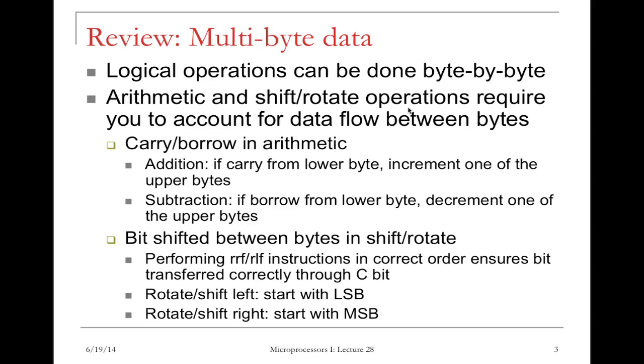Bit shift between bytes in shift and rotate. We'll make sure that the rotation instructions will go through the carry flag. For rotation shift to the left, we're going to start with the least significant byte. And for the rotation shift to the right, we're going to start with the most significant byte. Again, these are for multi-byte data.